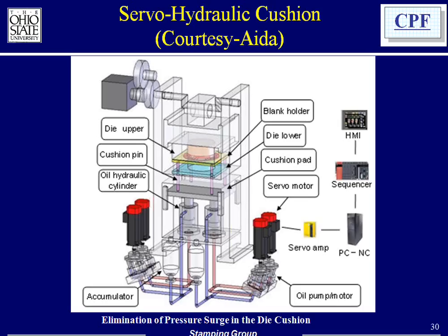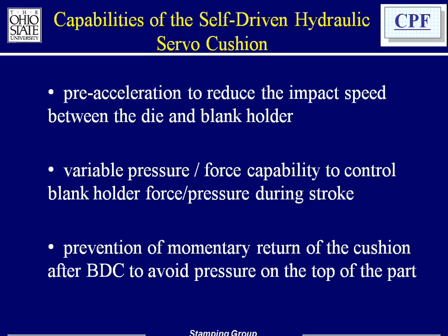through the hydraulic motors that you see in the bottom, and the servo motors are working as generators, and it generates electricity. In other words, in a hydraulic cushion today, when you press against the cushion, the energy that the cushion absorbs causes heat-up in the oil, and then you have cooling systems to cool the oil. But in this case, the oil pressure under the cushion is used to generate power and save electricity.